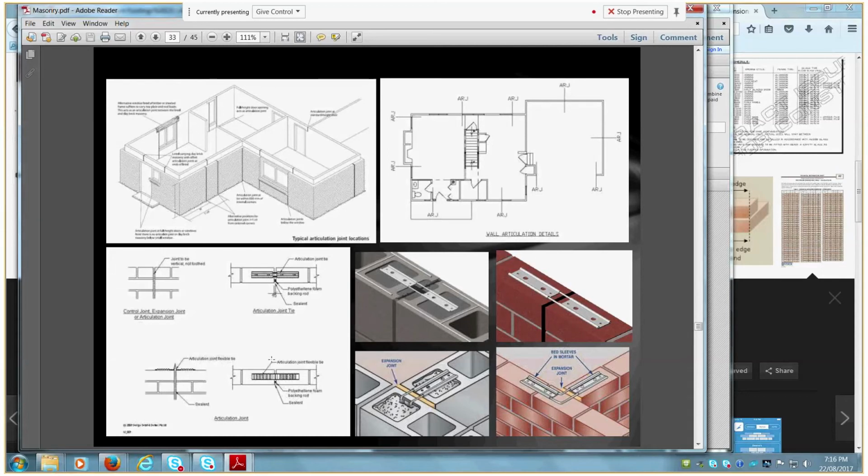Let's say it's fairly reactive soil, and the width of that is 6.5 meters. We'll have to have a control joint in there somewhere. So typically we'll denote that as being in the middle of the wall, so it can take up our expansion and contraction of our brickwork, and also that's the place that's more likely to open up, where we're going to get some flex in our slab.